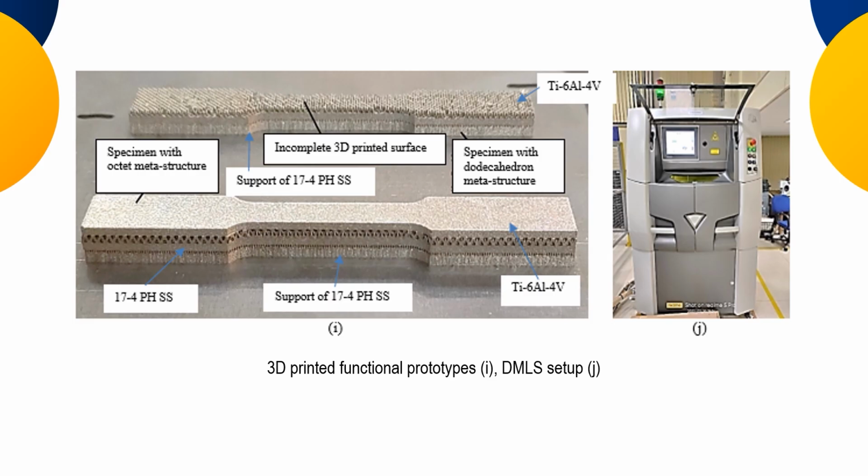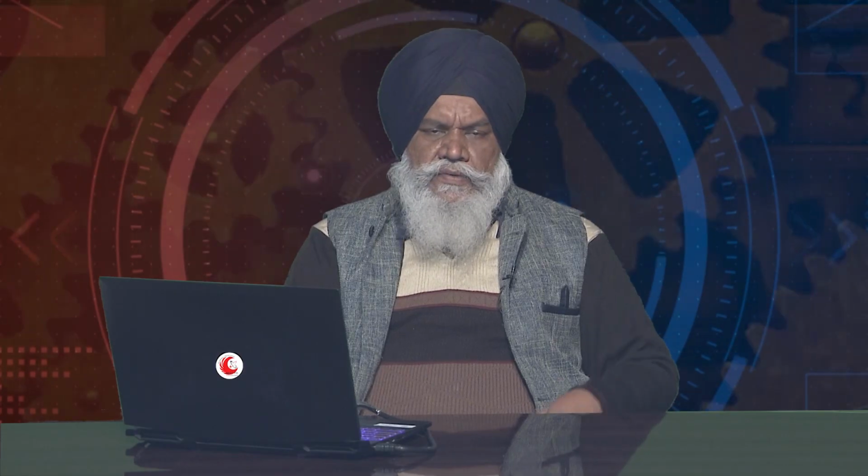So this is again the view of the 3D Systems DMP200 model that we have in our lab for the printing of this type of setup. So basically what we are doing, as we have seen in our metal printing case, I am interested to control the energy density, which is directly proportional to the laser power, and on the denominator side we have the scanning speed, the layer thickness, and the hatch distance. So basically the simple empirical relation helps me to control the energy density.